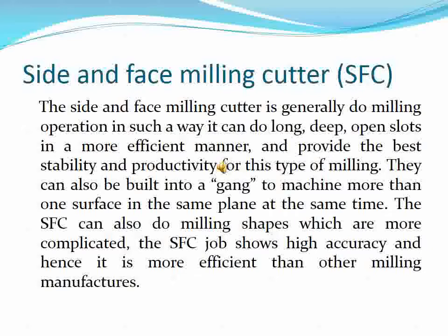Method of manual SFC. In the present method, the indexing is done manually by rotating the workpiece with a rod fixed in the indexing mechanism. The present method shows time variation in the same workpiece for a feed per tooth. Since the feed per tooth is manual and the operator will not consider the time given per feed to the tooth, the present method has difficulty in setting the angle of cut and also takes a prolonged time to index. The indexing mechanism placed below the table is a worm and worm wheel.